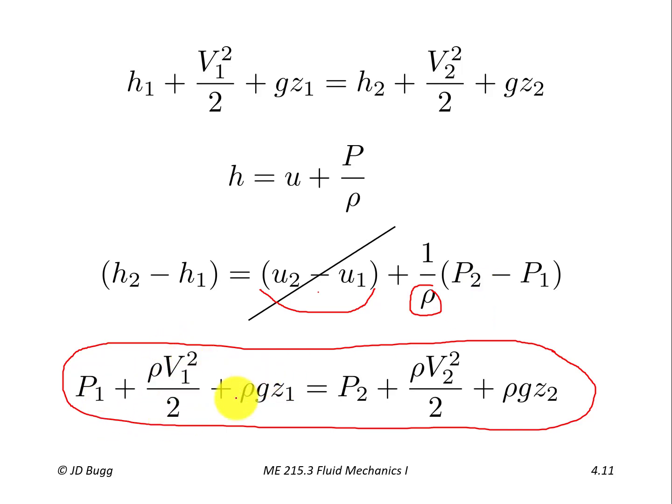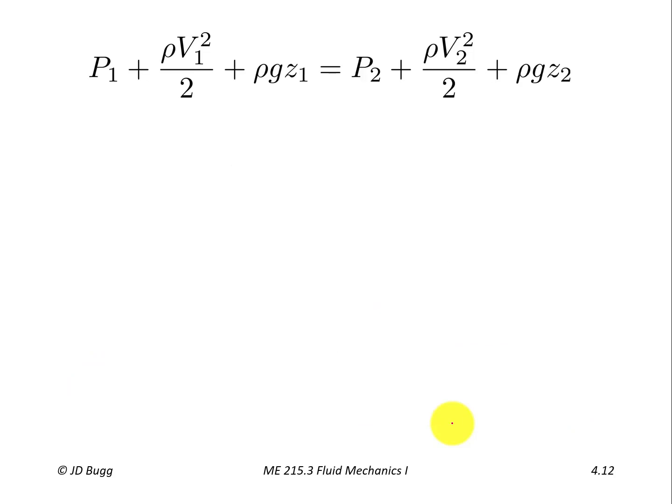Kinetic energy and potential energy. So the sum of those 3 terms at the inlet and at the exit, or at point 1 and point 2, has to remain the same because all of those other things, work, heat transfer, unsteady effects, have been set to 0. So it's an energy balance between those three contributions. So same equation here.